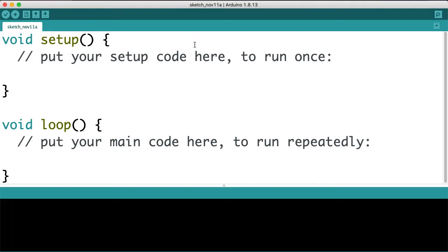is going to help us interface the LCD to the Arduino microcontroller, and there are a couple of ways in which you can do this. It depends with which protocol you are using. You can use a UART protocol, which is a universal asynchronous kind of connection. Then you can also use I squared C, or I2C if you want. It's also another method you can use, or you can use SPI.